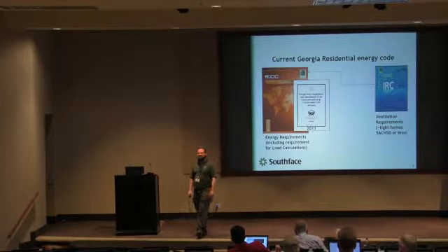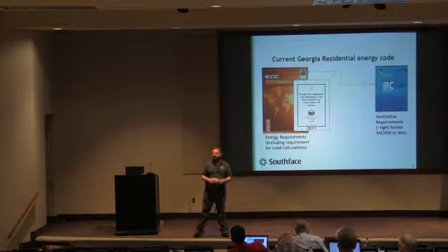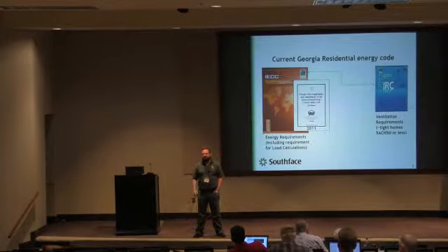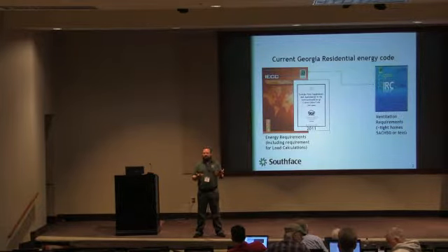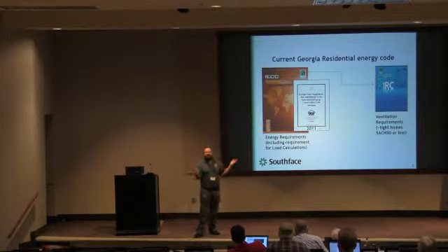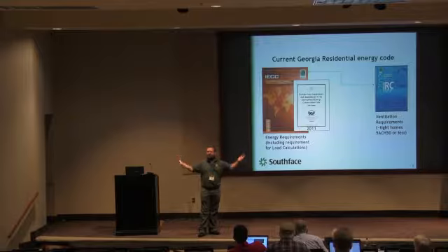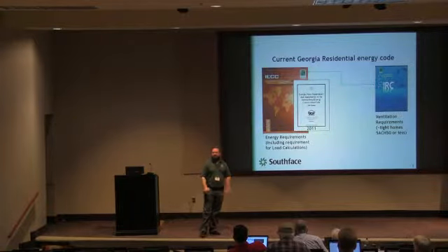It's by going with the higher unit because he already increased his ceiling insulation from R-30 to R-48. Yeah, so again, you have to assess what the conditions of the home are and what the loads are based on those conditions. If you don't do that, then you're guessing. Maybe it's a good guess, maybe it's a bad guess, but either way you're guessing.